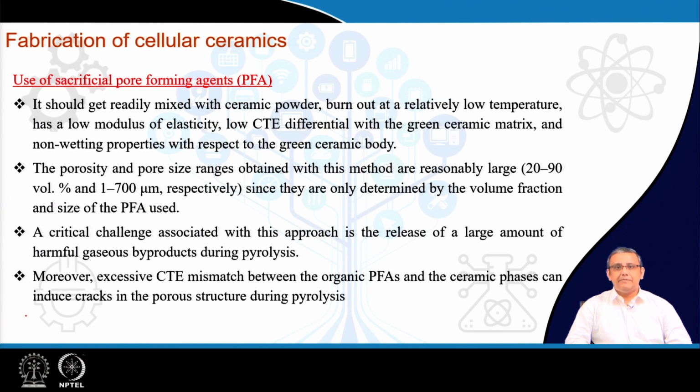Some of the properties of the pore forming agents are extremely important to give a good pore morphology and pore structure. The pore forming agents should have a sufficiently low melting point or decomposition temperature. They should also have a similar expansion coefficient as the ceramic matrix, because if the ceramic matrix and the pore forming agent have vastly different expansion coefficients, that might give rise to cracks inside the body because of thermal expansion differentiation.